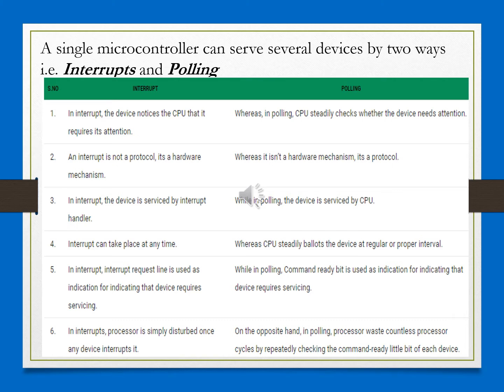Generally in a round robin fashion, each of the devices will be checked for a flag condition. This would be a time-consuming situation for the microcontroller, because for every device it has to check the status of the flag, which would be an indication that a service is required.